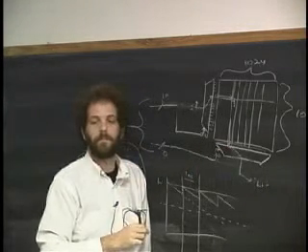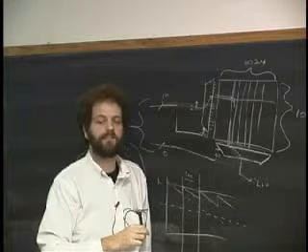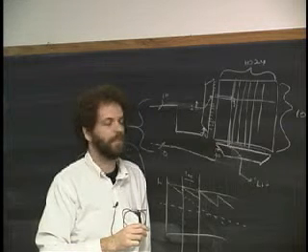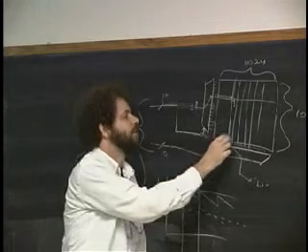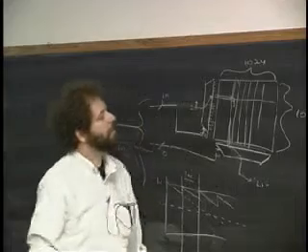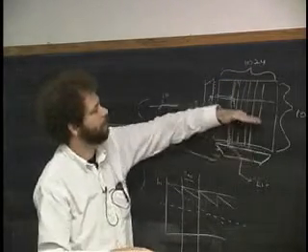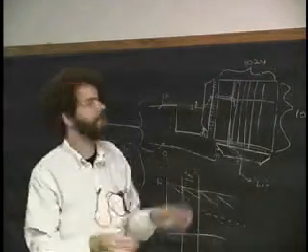Does the amplifier know the address from which it was coming, and amplify by a different amount? That's an excellent question. By saying, well, that guy was farther away, so he needs to be boosted by a greater amount? That's absolutely right, and the answer is yes. Okay, so they actually do that. They actually know that there's a scaling law between what happens down here and what happens way up here. In fact, they usually have two sets of amplifiers. They have one down here and they have one up here. This one gets it from this half of the chip down. This one gets it from this half of the chip up. There's all kinds of other tricks.